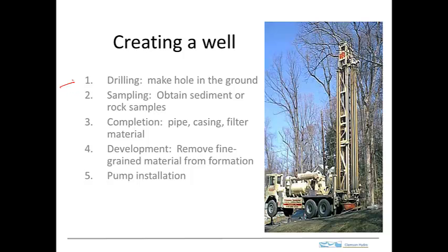So to create a well, you first of all have to drill a hole in the ground. Some cases you may sample the cuttings coming out, but maybe not, depends on what the needs are. And then once you have the hole in the ground, you have to what's called complete the well, and that changes the well from being just a hole to being something that would be durable and lasting and isn't going to collapse.